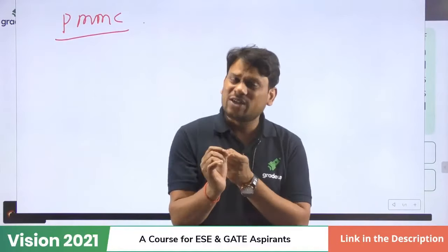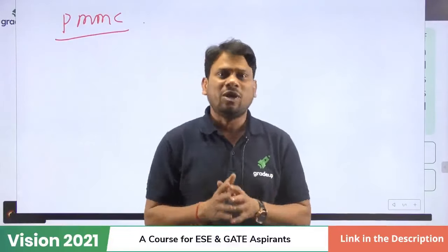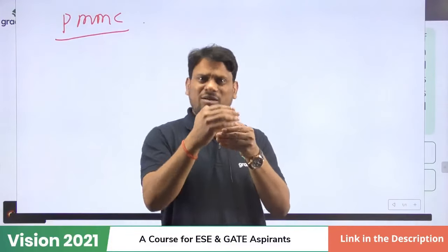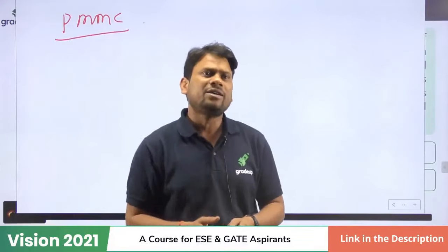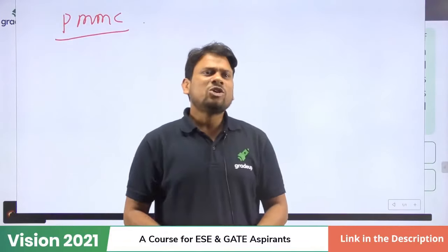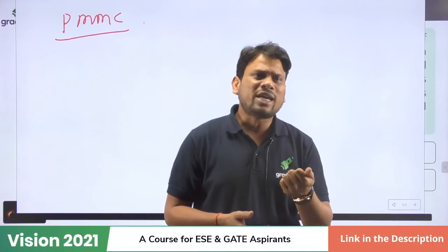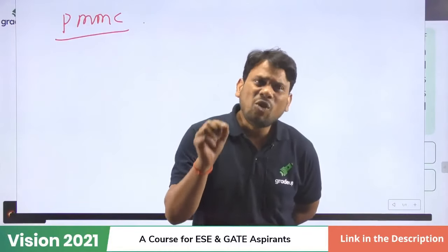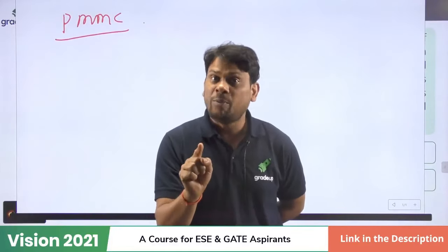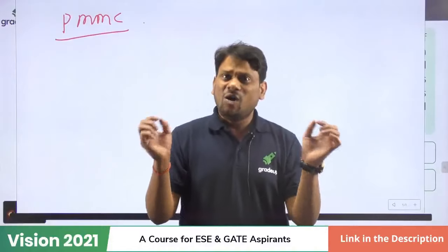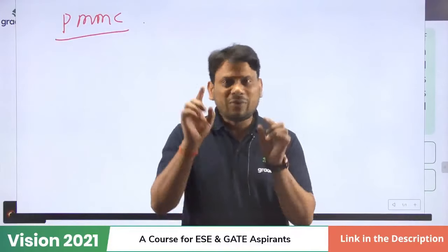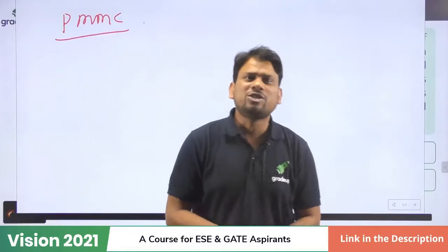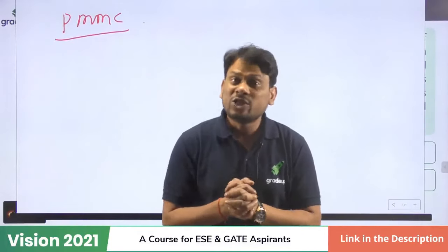PMMC can read 0 Hz signal or non-0 Hz signal also. Please somebody reply. Do it fast. PMMC can read 0 Hz signal or not equal to 0 Hz signal also. Yeah, Nikhil, thank you. So, sir, can PMMC measure non-sinusoidal wave AC signal? Yes, Anupam, please listen to me everyone. PMMC can measure non-sinusoidal wave signal also, but most important thing, the average area of that signal should not be 0. If that area is 0, our pointer will indicate 0 value.